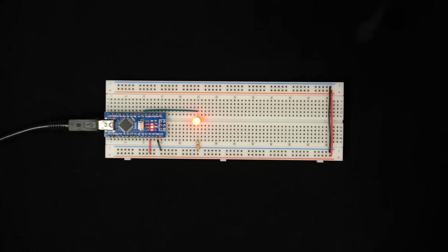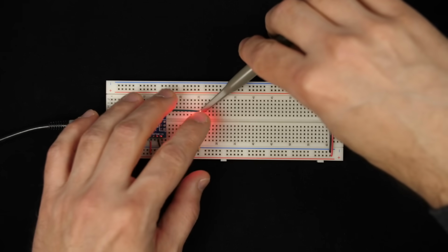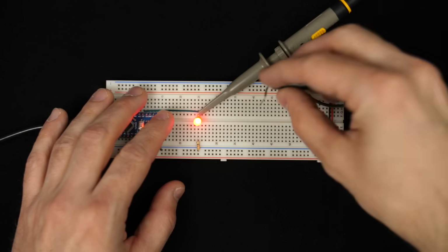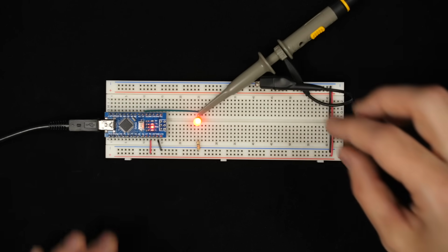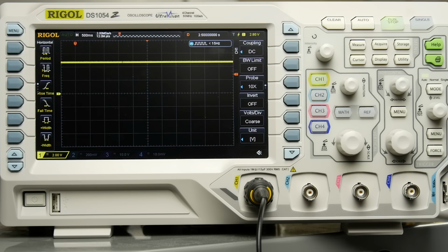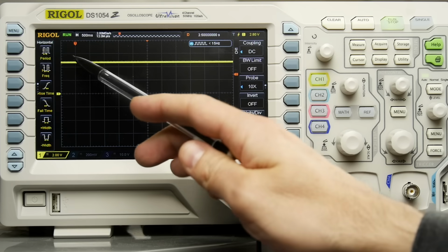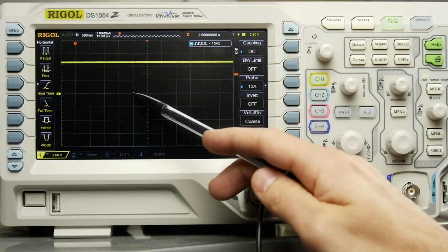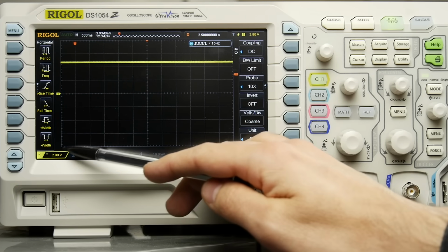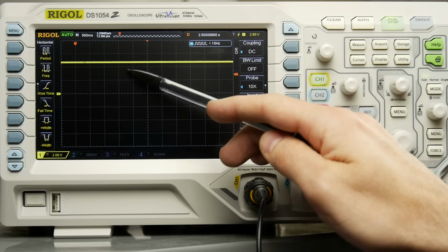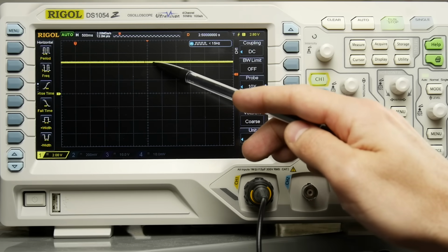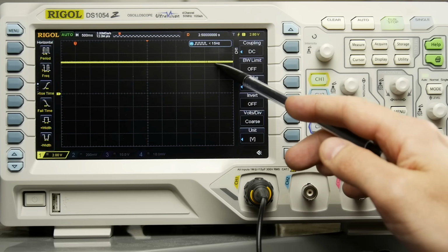So what I'm going to do is hook it up to an oscilloscope that will actually graph the voltage over time and give us a way to quickly see exactly what it's doing. And so now if we look at the scope, what we see is that our voltage is up here at 5 volts. So 0 is here in the middle, and then it's 2 volts per division. So 2 volts, 4 volts, and this is almost 5 volts here. And so it's just constantly here at 5 volts.